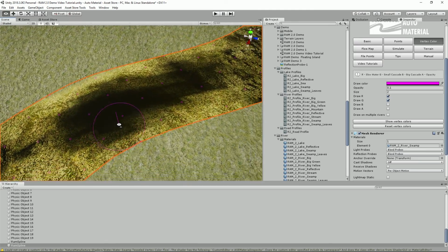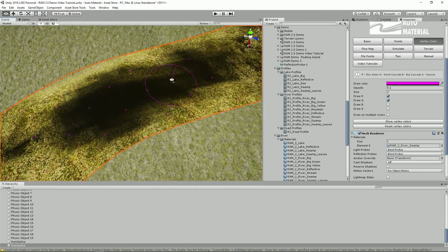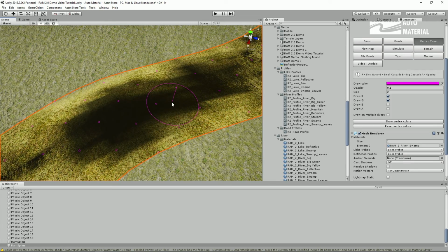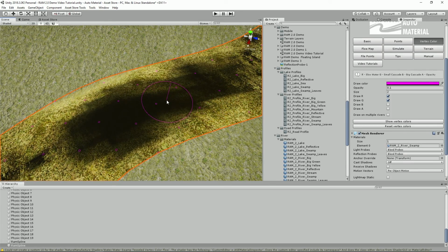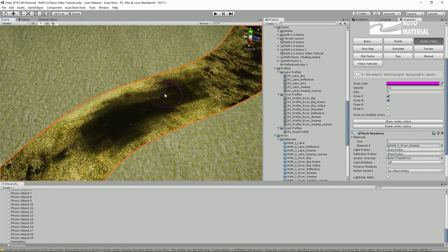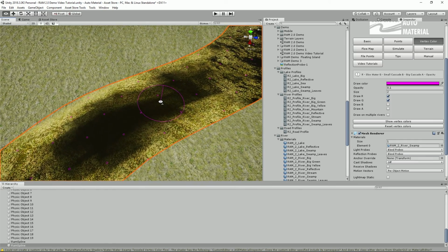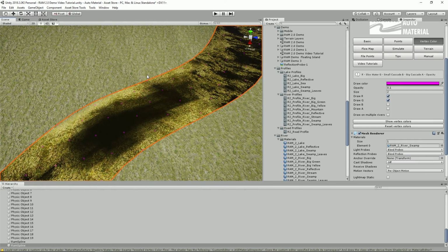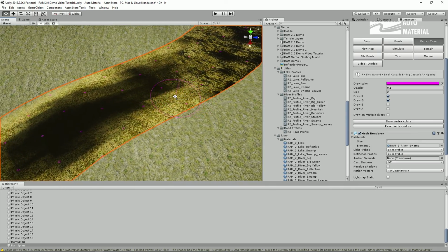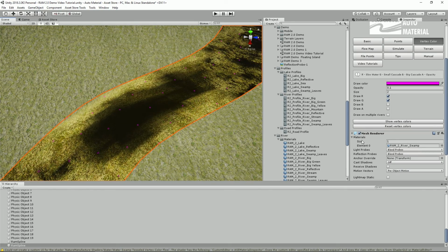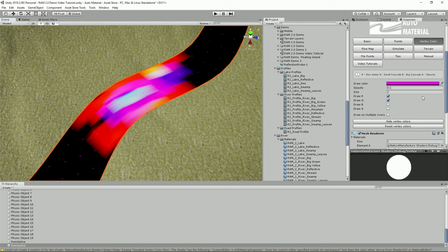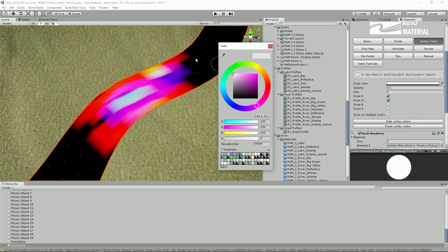We advise to play with this, play with different materials, sometimes even not our materials, just material which support vertex color. For example, a road which is covered by snow. On R channel you could hold snow, on G channel wet snow, and for example on B channel raw asphalt. We have of course debug for vertex color, so you are able to see what exactly is on our spline.